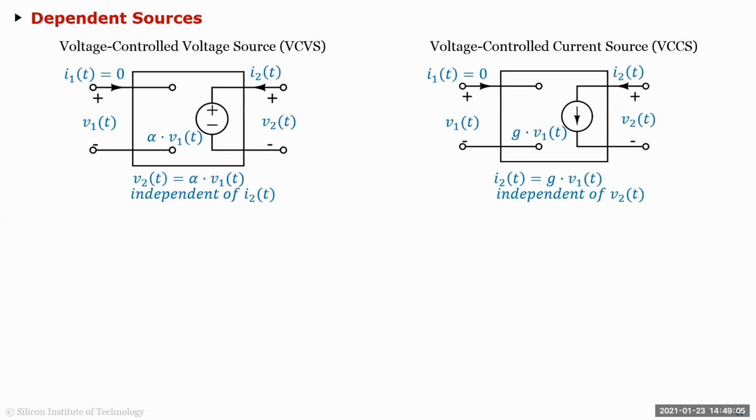And this is the basis of an amplifier too. See, an op amp is not an amplifier. An op amp is a result of an amplifier. But the basic element of an amplifier has to be a transconductance. That's one key thing you have to remember. A lot of times people will ask you in interviews, what's an amplifier? For example, is a transformer an amplifier? Let's say a 2:1 transformer. You give an input voltage, and the output voltage is twice that. Is it an amplifier?